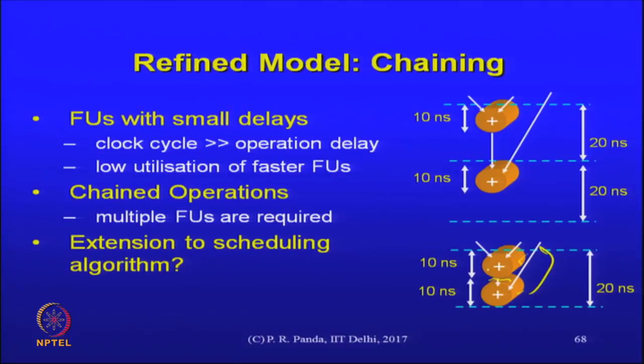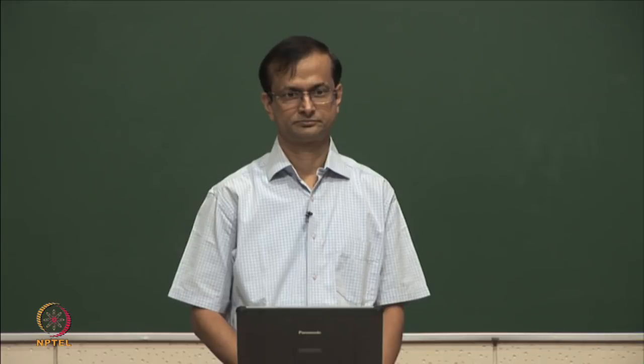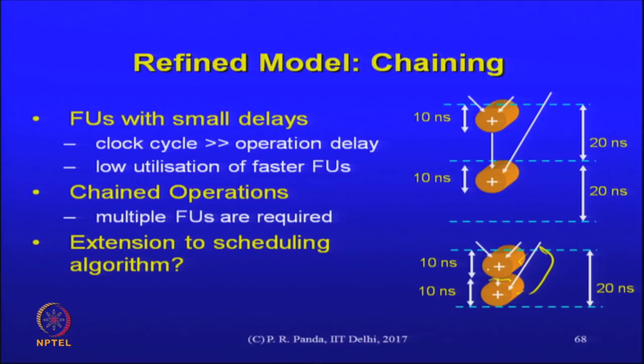How do you change the scheduler for this? So now we look at the downstream nodes also for the dependency. We can't live with the current method as is, because we don't know if a register was needed in between. But remember, at the scheduling time, we don't worry about registers. Registers are inferred, but that happens at a later stage. We don't have to worry about whether we have put a register already or not.